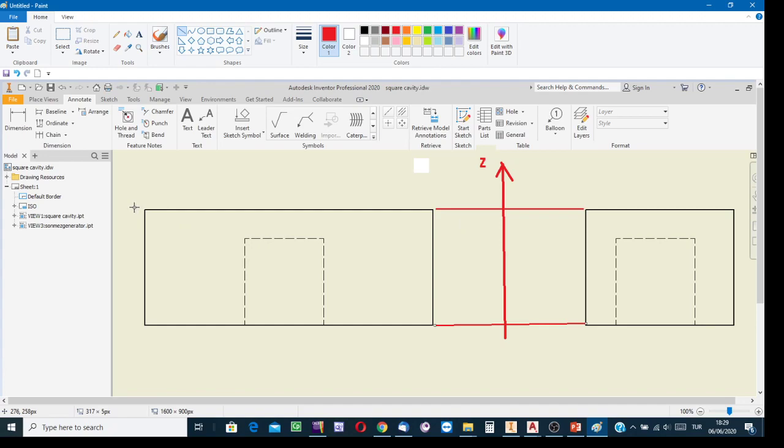You see the front view is between this transfer line and that transfer line. Since the z-axis is commonly used, if the front view of the object is between those transfer lines, then its left side view must be between the same transfer lines. At the view reading stage, following the transfer lines, between them we have the image of a certain feature, and finding correspondingly on the other picture plane the image of the selected entity, we can say something on its shape.